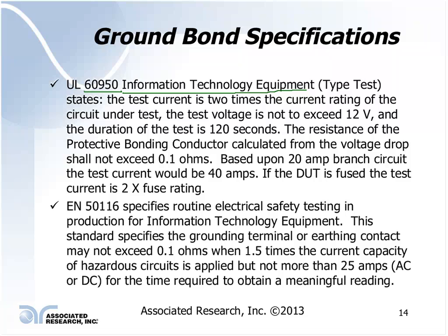It takes about 3 to 4 seconds for that paper clip to turn red hot and fail. Based upon that, I would say, if it takes that long to melt a paper clip and cause a failure, probably a 1-second test is not sufficient to test that ground circuit.